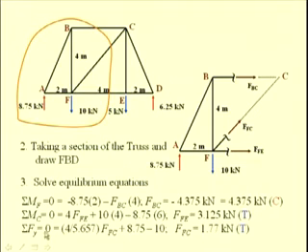For the third equation, we can take either a force summation about the x axis or a force summation about the y axis. Here we have taken the force summation about the y axis and we have equated it to 0. From geometry we get the direction cosine of this force FC.